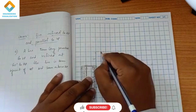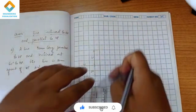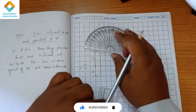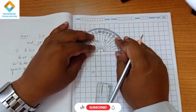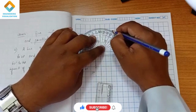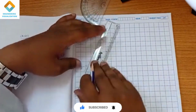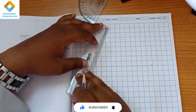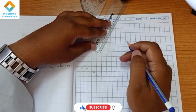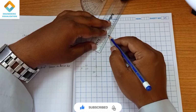Here, at the end of the line, you have to give the angle first. It is inclined to HP. Whatever the inclination to HP, it is seen in the front view. So here I am going to mark an angle of 60 degree, and here I am going to draw a line of length 60 mm. 1, 2, 3, 4, 5, 6.